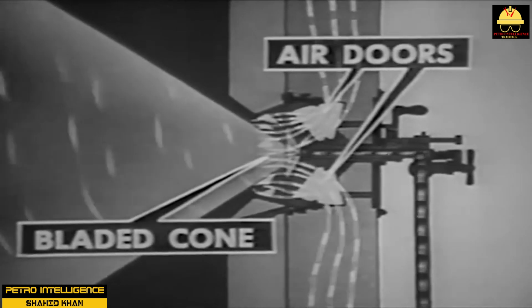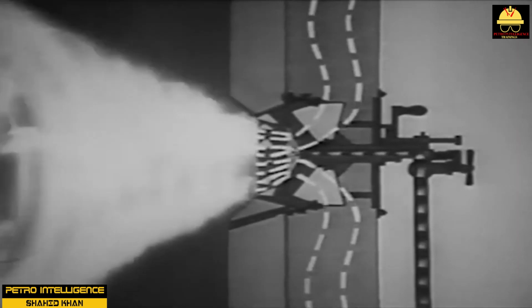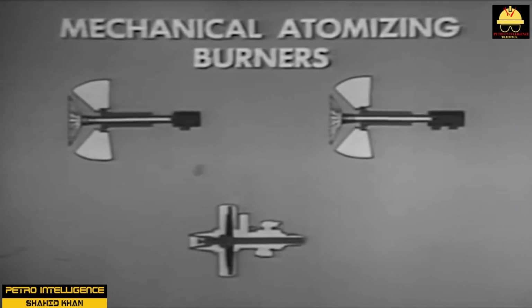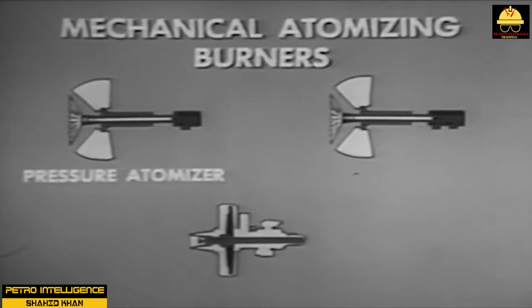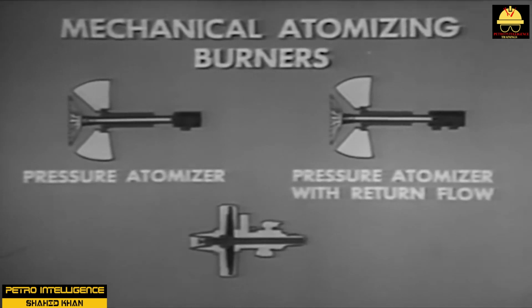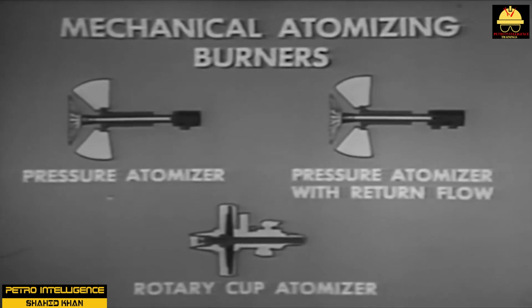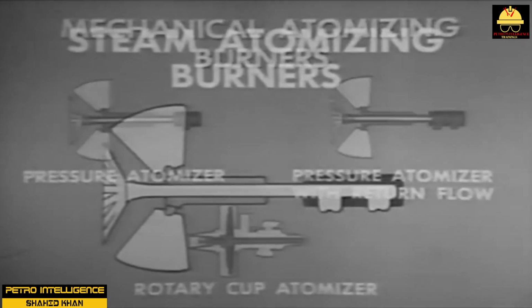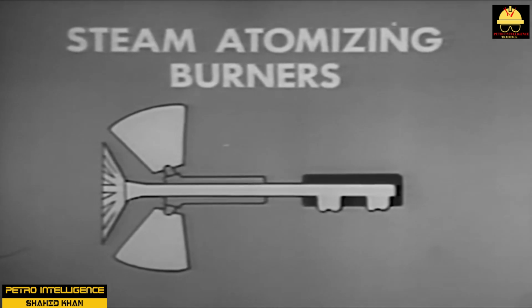Combination burners make furnace operation and fuel distribution more flexible because they combine two burners, gas and oil. This type of burner can use either gas or oil or both at the same time. Low nitrogen oxide (NOx) burners are designed to be operated with lower amounts of excess air than typical burners. The use of a tertiary air register reduces nitrogen oxides in the flue gas stream. Raw gas burners combine gas and air in the furnace, which ignite at the discharge. They use only secondary air, and the registers must be reset if the rate changes.